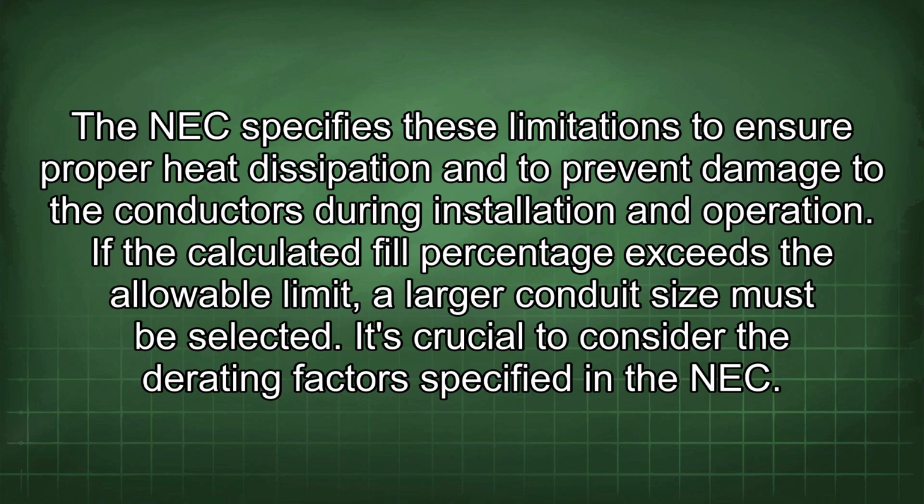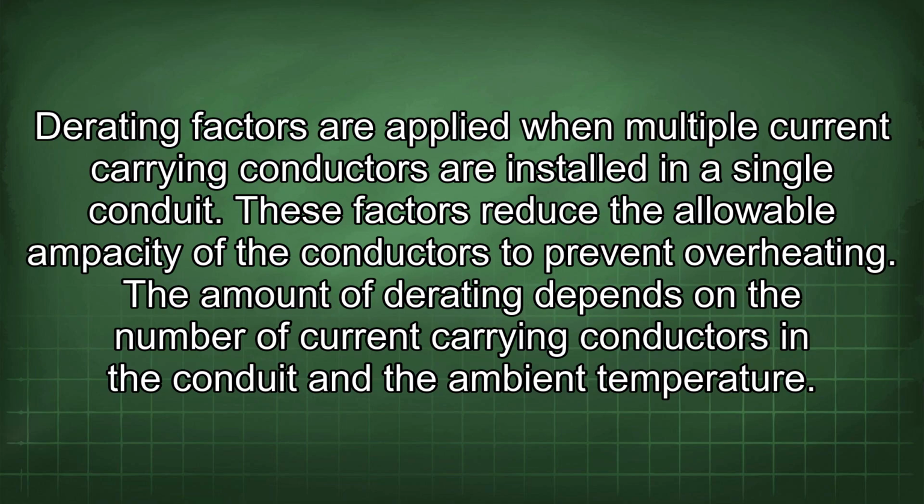It's crucial to consider the derating factors specified in the NEC. Derating factors are applied when multiple current-carrying conductors are installed in a single conduit. These factors reduce the allowable ampacity of the conductors to prevent overheating. The amount of derating depends on the number of current-carrying conductors in the conduit and the ambient temperature.